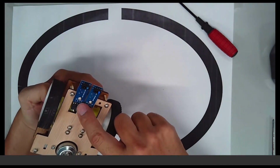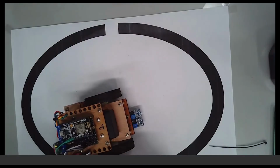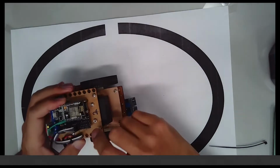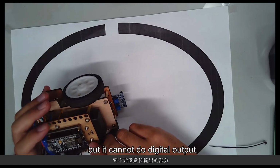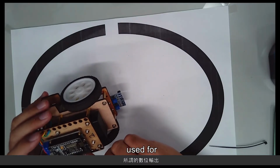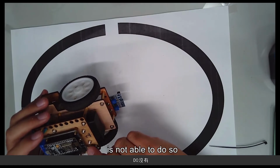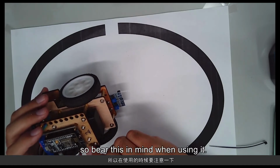Likewise, black for VCC and white for GND. Now we're going to do the wiring. We need to connect the pin to D0. The D0 pin is quite special. It can only do digital input, but it cannot do digital output. Therefore, when using this D0 pin, the pins D1 to D8 can be used for PWM output. Only D0 is not able to do so and can only do digital input. So bear this in mind when using it.